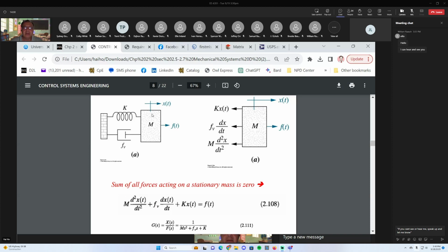The way you determine the differential equation of a system like this is you draw a free body diagram. A free body diagram starts with the point where you define the displacement variable, like x. If you define x to be the displacement of the mass, then you draw the mass here and you say x here, right here is where x is 0, and x gets larger as the mass moves toward that direction, or x gets more negative as the mass moves toward the left.